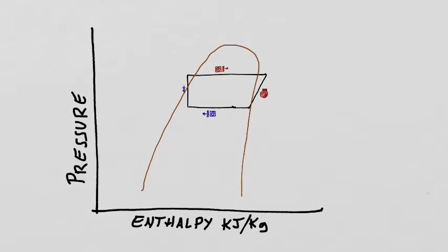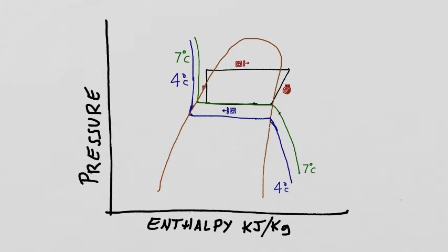By placing our refrigerant diagram into a pressure enthalpy chart, we can read off the enthalpy, or heat energy, at different stages of the refrigerant process. In our pressure enthalpy diagram, the pressure increases along the vertical axis, and our enthalpy, heat energy, increases along the horizontal axis. Our temperature tracks through like so.